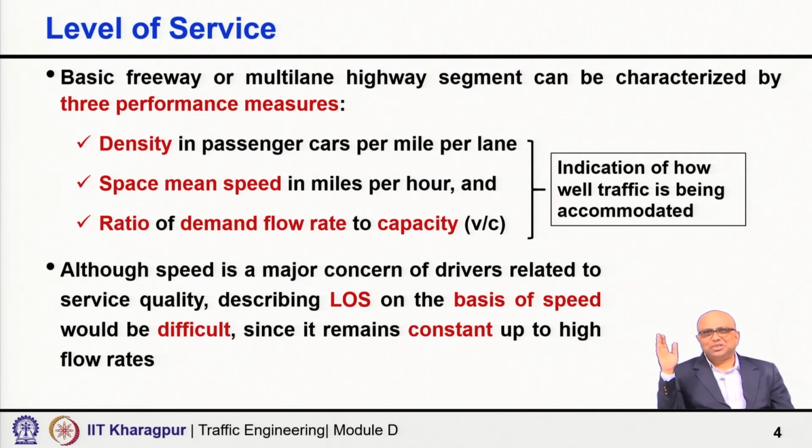As you have seen in the three segments of the speed flow curves as expected for freeways and multi-lane segments, up to quite a high volume or flow level, the speed is nearly constant. So if we use speed, how will we consider variation with the flow, especially up to that break point? The entire range may operate with the same speed.